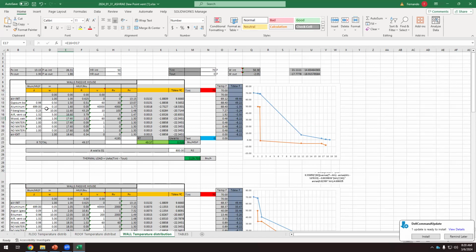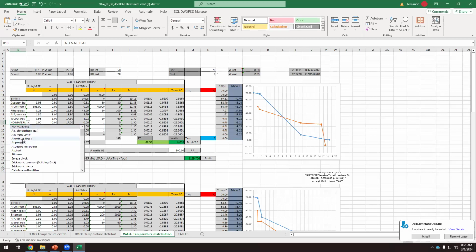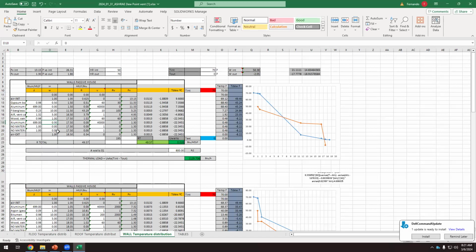And it has to be here because if I imagine that I don't have this here, so that's 0, and I add another material. I have the drop down list. If I have here aluminum, and this is 1/10, what happens? That happens. So it's not a question of, I place the vapor retarder and it works. It works if it's placed in the right position, in the internal phase of the thermal insulation. If I apply the vapor retarder on the external phase of the thermal insulation, it will be a disaster.